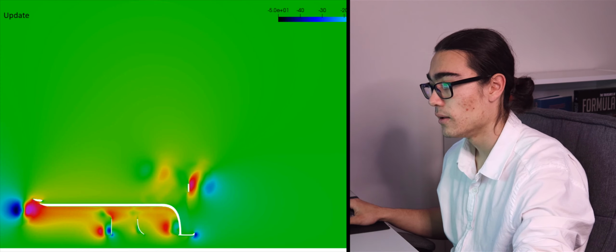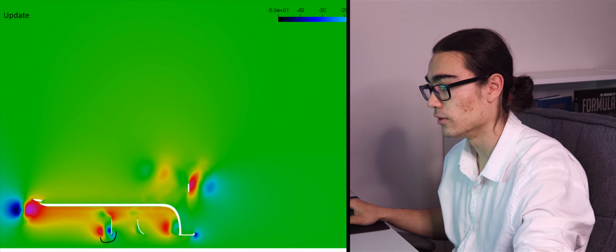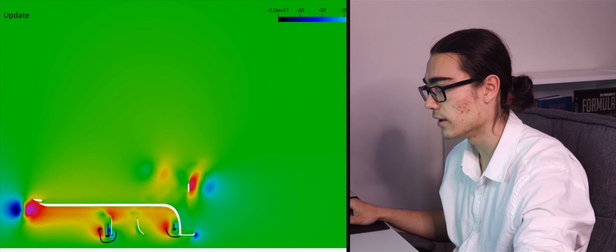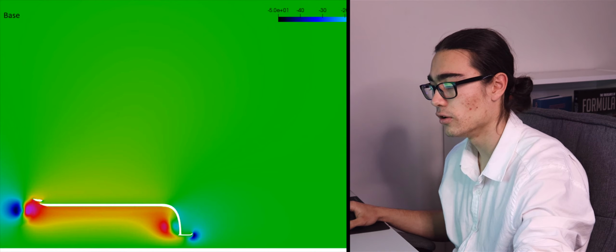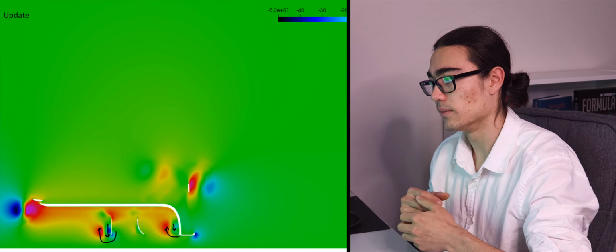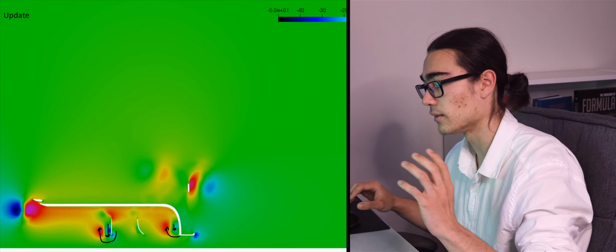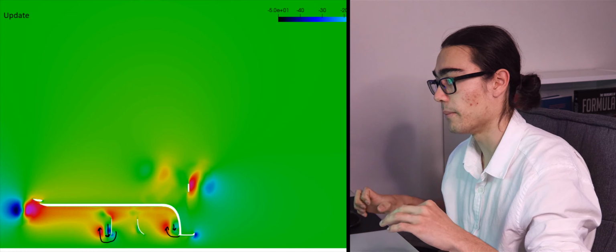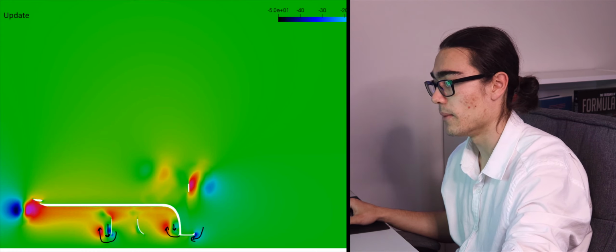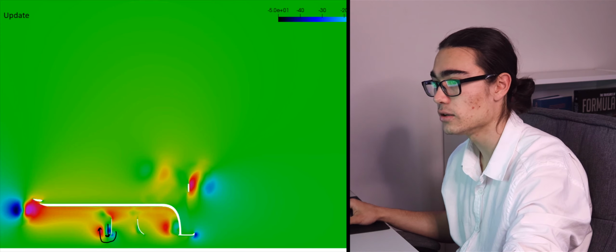Well, firstly, here is our straight vortex. So we've got an upwashing side here, and we've got a downwashing side there. Now that's normal, and that's what we'd expect. We can see this vortex here, which is the same as the last case. But if I flick, it's a much smaller magnitude, which is, again, as we'd expect, because we discussed there were multiple reasons why perhaps we were getting less in-wash through here. One being maybe that we added the end plate, and that's made a bit of a change.